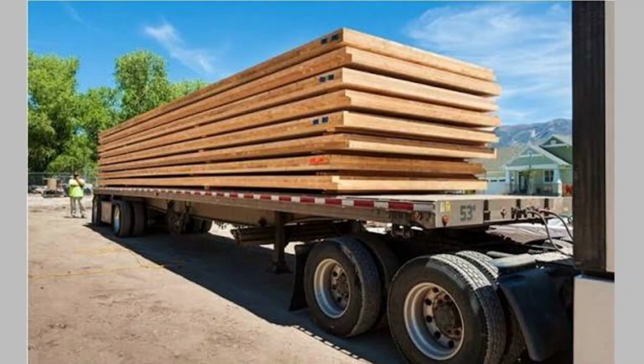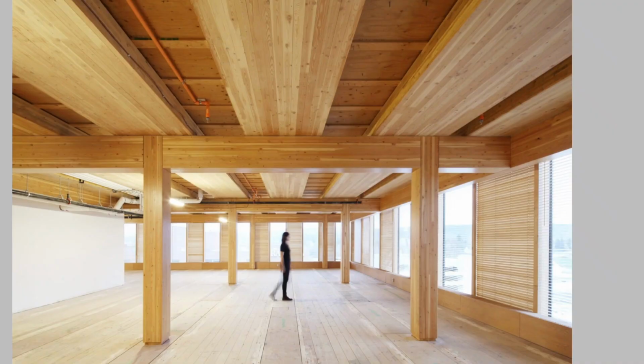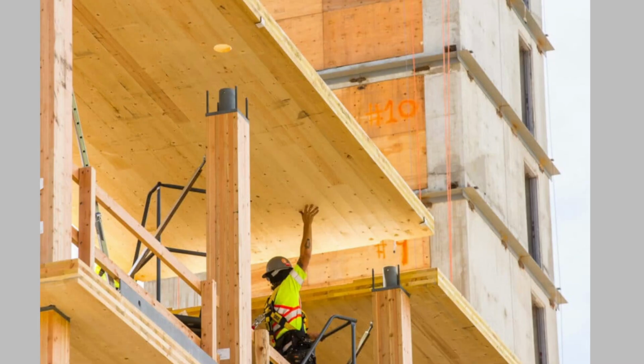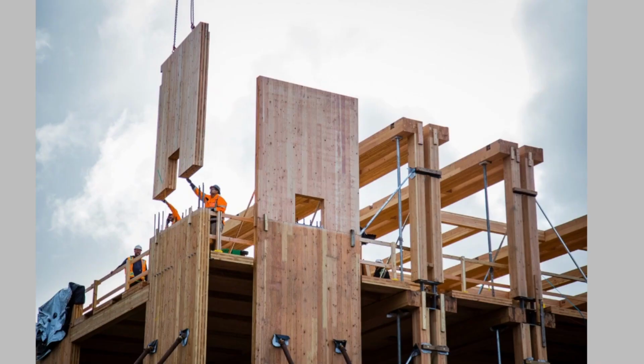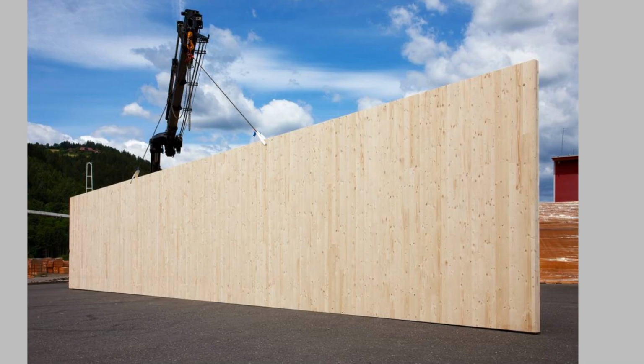Structural uses. Floors and roofs, spanning 6 to 9 meters without beams. Load-bearing and non-load-bearing walls. Shear cores for elevators and stairs, replacing concrete cores in many mid-rise buildings. Modular volumetric units, entire rooms built off-site. Speed advantage. Frames that take months in concrete can be erected in weeks with CLT.